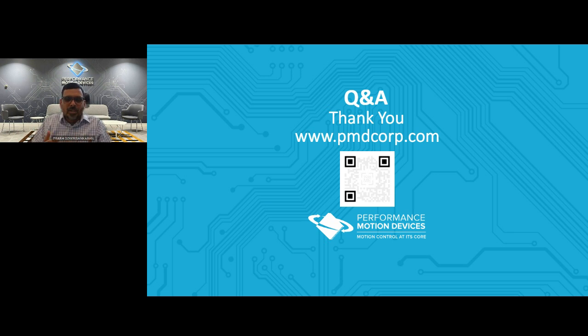that can upload data to the cloud. The other implementation we've seen is one per axle. So you have two drives, and there's one per axle, and there they have a CPU on board that's collecting all the sensor data. The drives are just doing the position loop and the current loop and all that. And so the central controllers, there they have a centralized architecture where they put both the drives in a flat network. So that's the comparison.